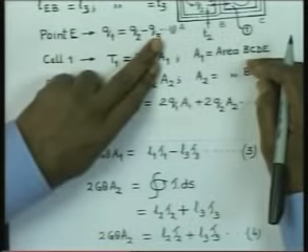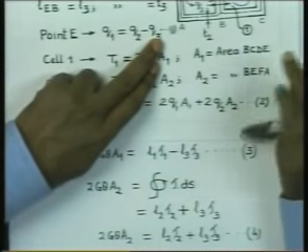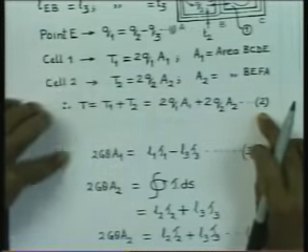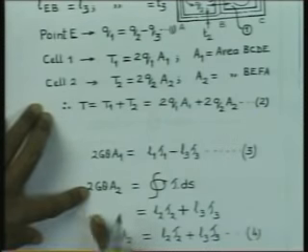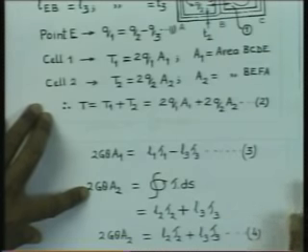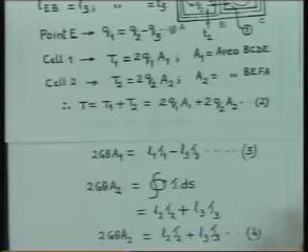So, to sum up, finally from this derivation what we have got are the 4 relationships. We have condition 1, then the torque related to the flows, and the angle of twist related to the shear stresses. Therefore you have the unknowns, the 3 shear stresses or 3 shear flows and the angle of twist, and you have 4 equations, so you can solve for them.